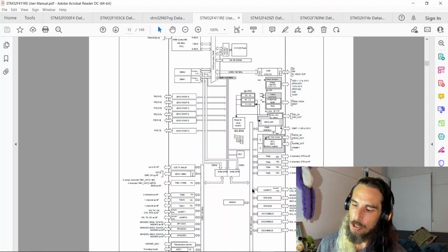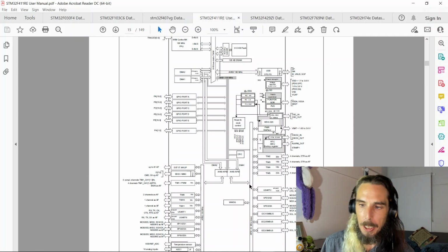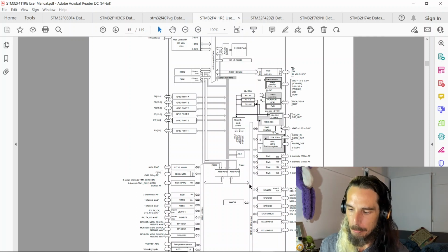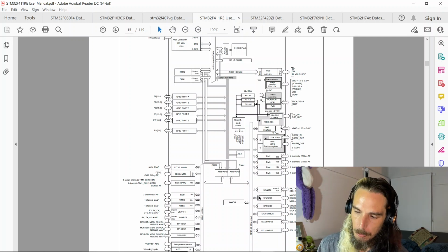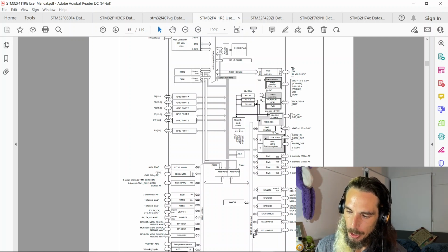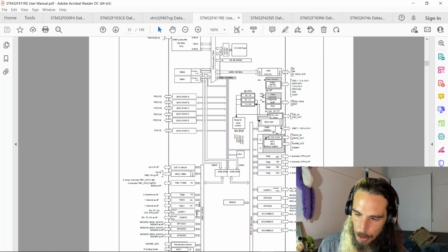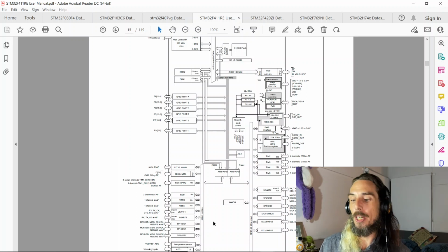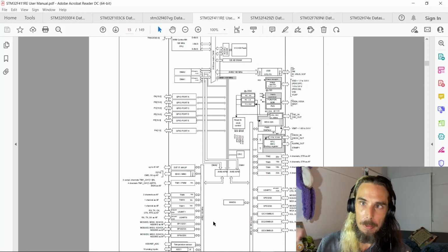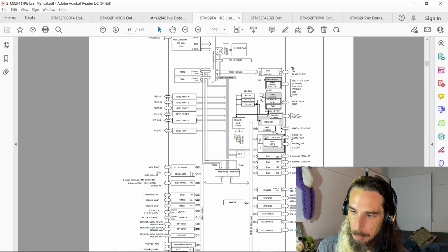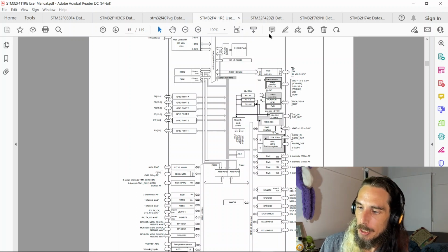And in that situation, depending on how much congestion there is on that particular bus, it might be worth actually not using one of the SPI peripherals on APB1. It might be worth using one of the ones that's on APB2, so that you're spreading the load and not clogging the buses up as much. So it can be handy to be aware of that.